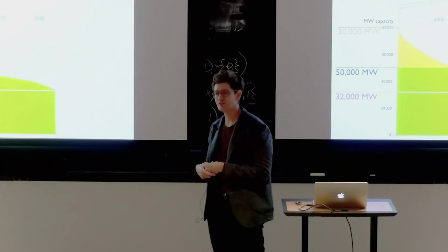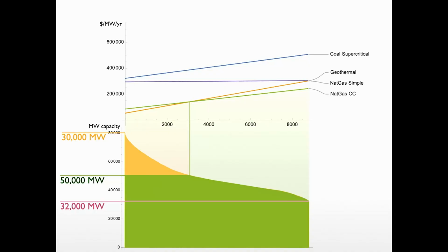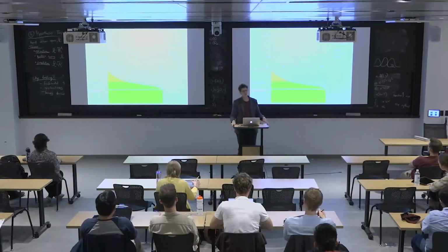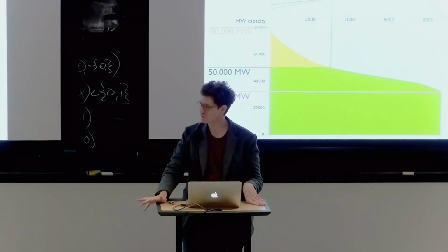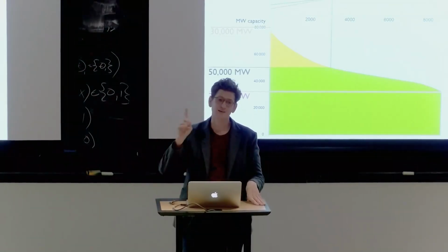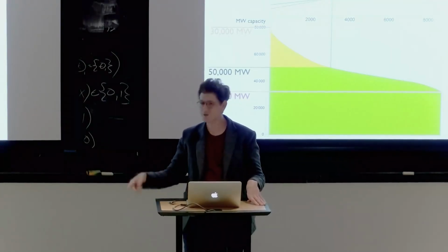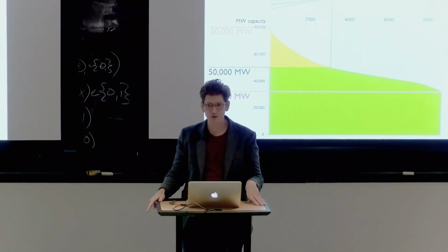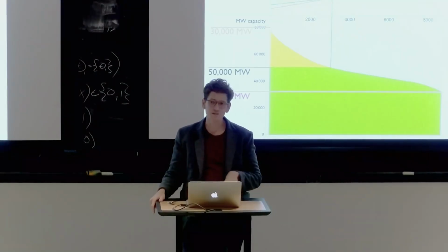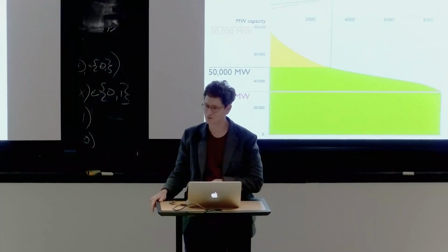Baseload will simply be the technology which is the lowest on this end of the graph. That's what will be dispatched as baseload. There's no special properties of a generator that make it suitable for baseload. However, the inverse is not true. There are properties of generators that make them unsuitable for non-baseload applications. So the correct statement is not we need nuclear for baseload. The correct statement is nuclear is really only suitable for baseload.